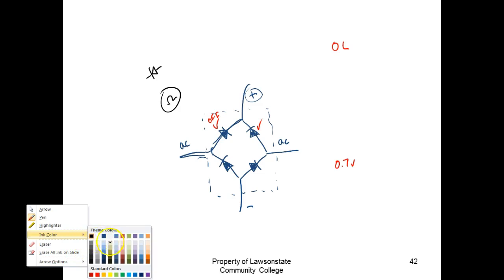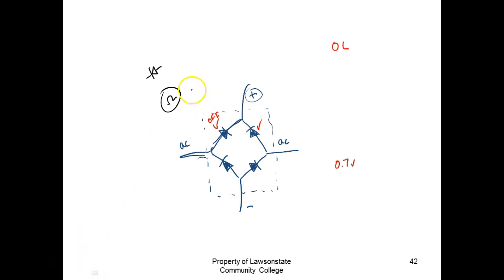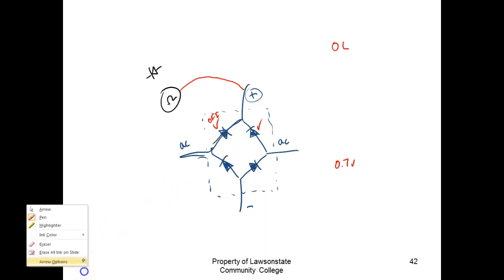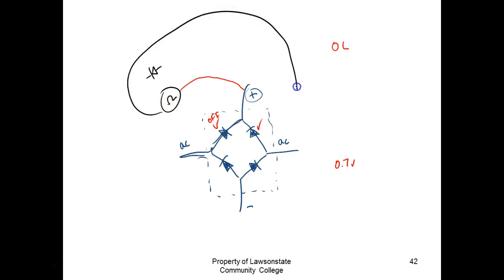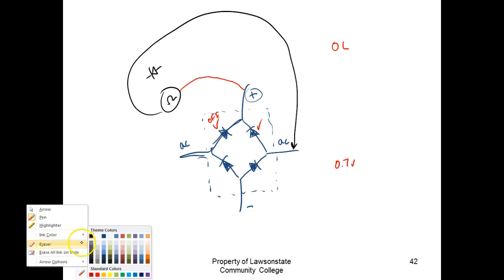Yeah, that's what we're trying to do. So don't just check a diode to see if it works forward bias. You need to always check it to see what happens when you reverse bias. And now we're checking the reverse bias on this diode right here, right? Right? Okay.